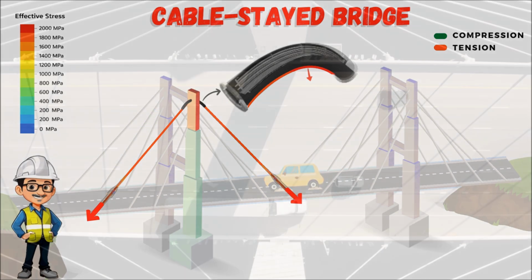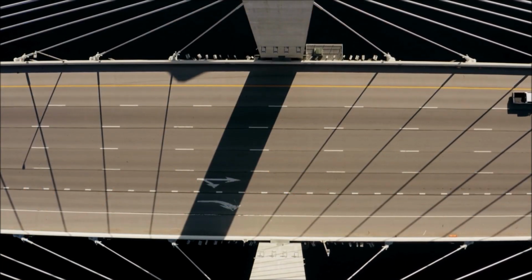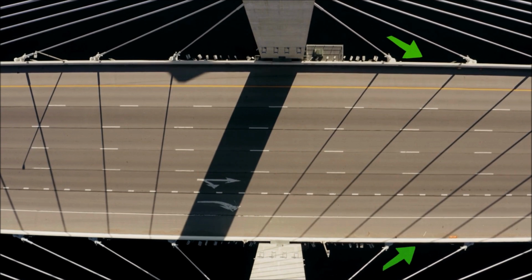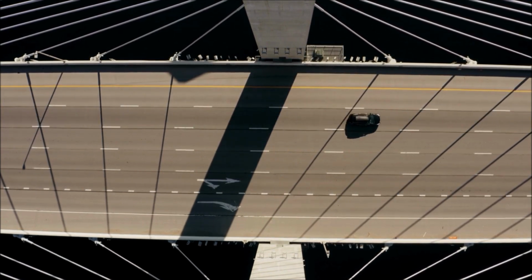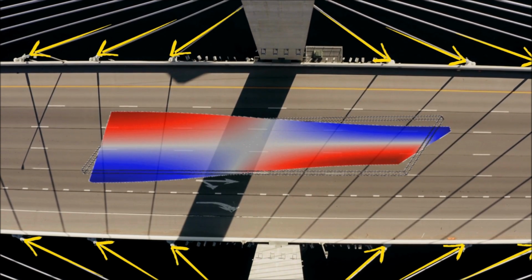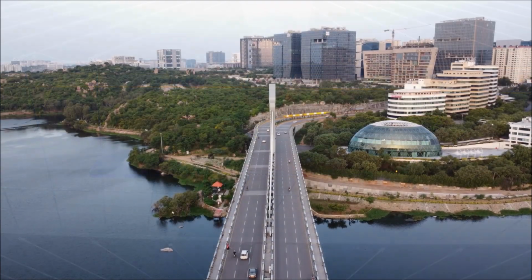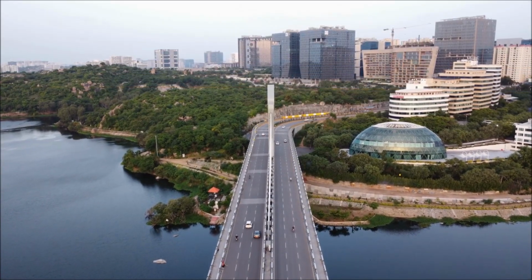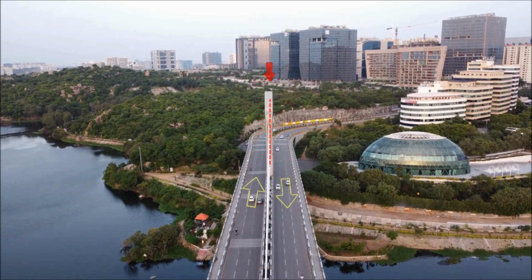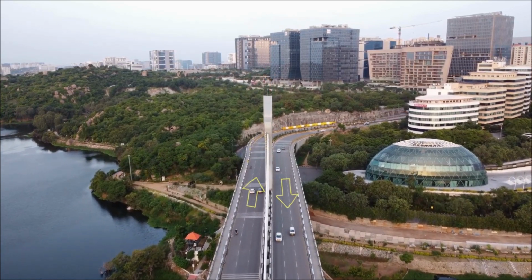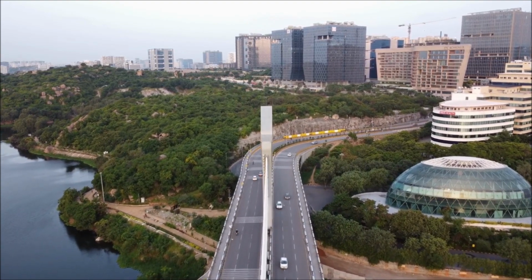Generally, in conventional cable-stayed bridges, the cables are typically in two planes separated by the width of the roadway, providing balanced load transfer and minimizing torsional effect. But there are some recent modern bridges where you can see the cable stays in the central plane between the two opposing lanes of traffic, which requires the superstructure to be designed for torsional resistance.